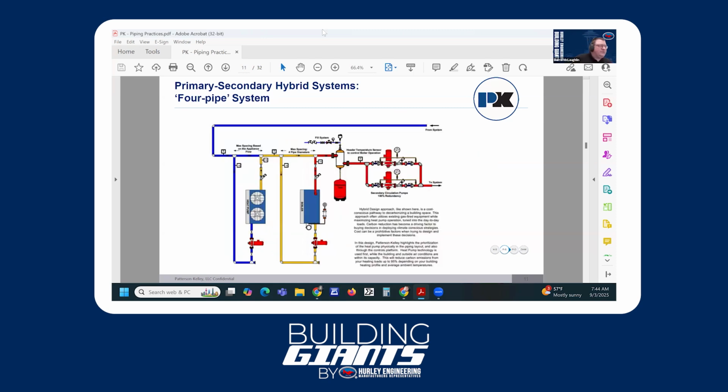So here's our first introduction to adding a heat pump. So a heat pump is the same thing. Technically, even though this is a condensing boiler, the heat pump is considered our more efficient appliance. So we're going to put it upstream of the condensing boiler. Fewer emissions, better efficiency, and then lower carbon footprint if that's the concern for your environment, your area. So we're doing the same thing though. It's still a primary secondary setup.